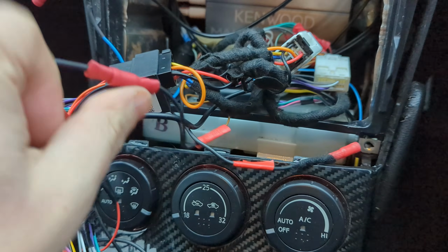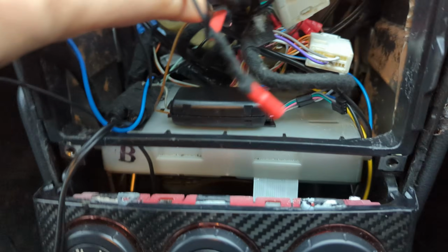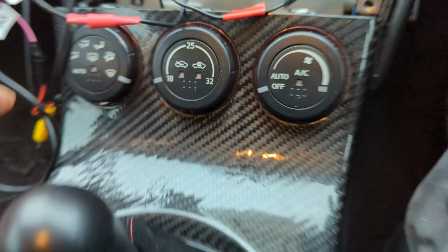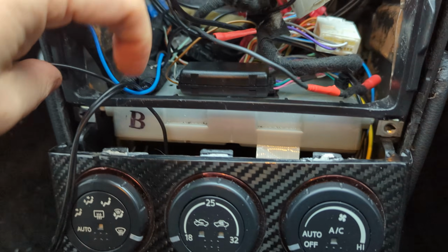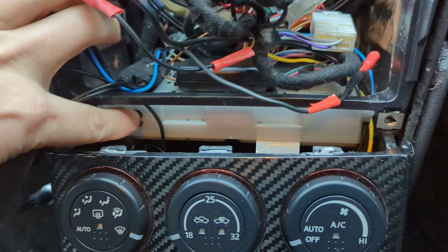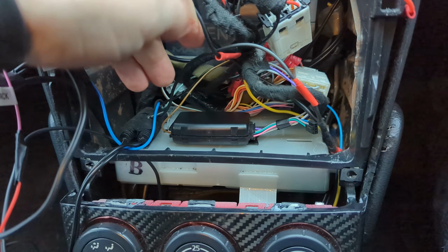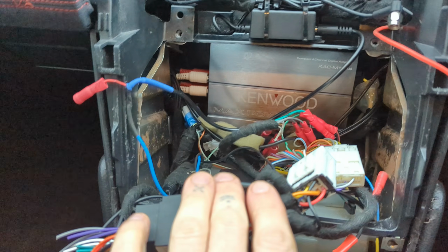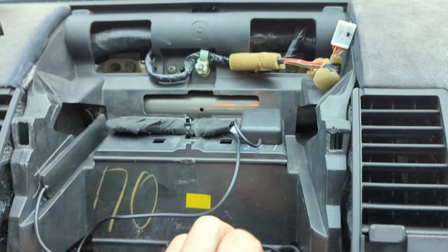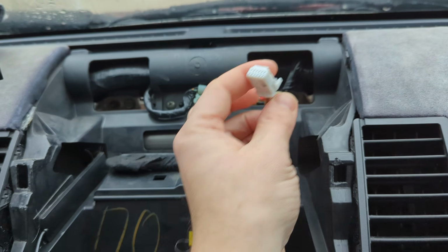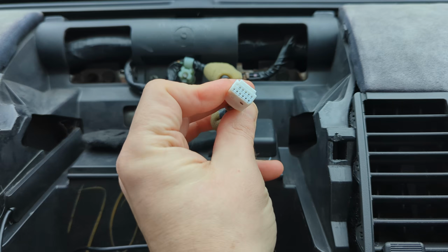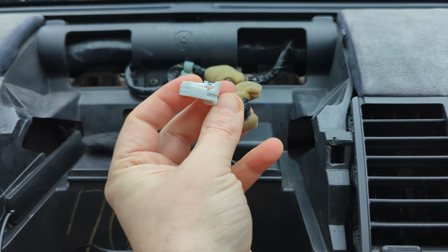Down at the bottom of the center console, underneath the gator surround, is this little box, and it's called the unified meter. What we have in here is a bunch of the sensors from around the car, which get fed into this box and then redistributed to parts of the car. Part of that involves sending the battery voltage and the oil pressure as analog signals up to this little clip, which goes into the back of the triple meter.